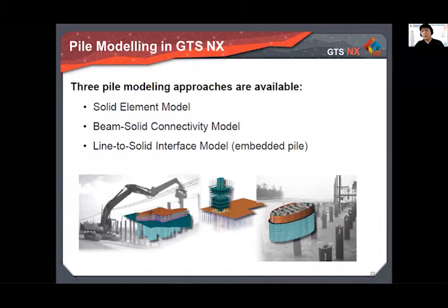So when we use geotechnical software, in this presentation we are using GTS-NX from Midas, we can model piles with three different approaches. In general, in a 3D numerical model, you can simply consider the pile itself with solid elements, but sometimes it is more efficient to use only the line type pile element, for example if we have a pile foundation with a number of piles.